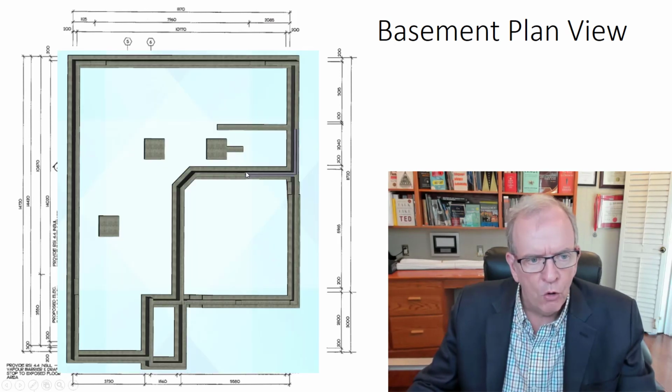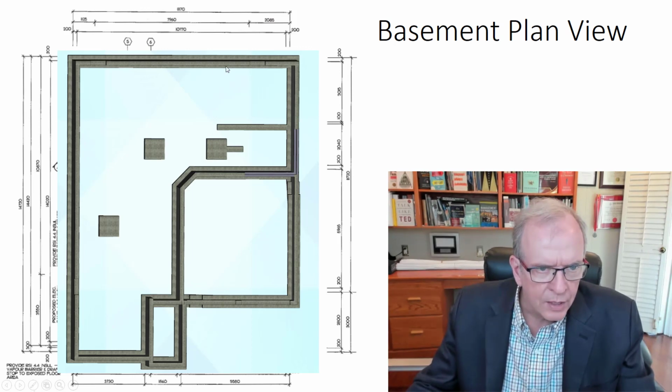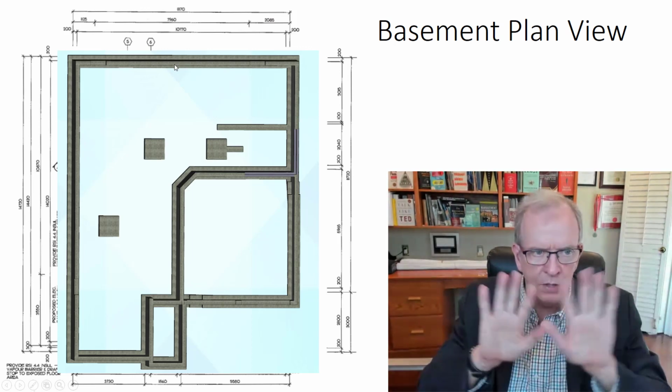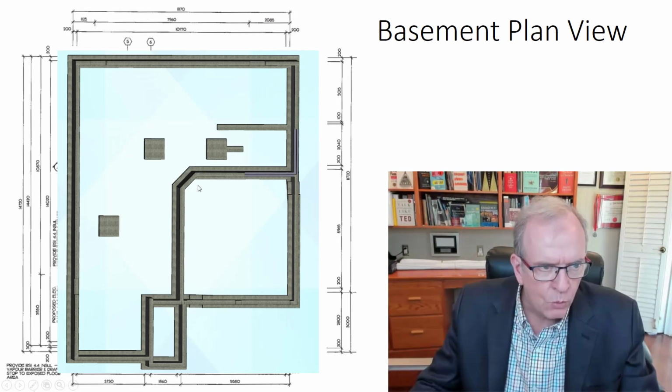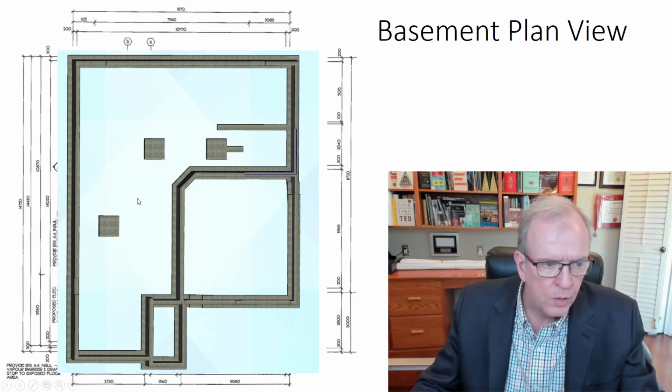I've just overlaid this 3D image of a 3D model for this particular house. You can see the outside, and it's in a perspective view, not an orthographic one, so you can see a little bit down some of the walls, and you see some shadow lines here. And you can see this little cutout here, which we'll talk about in a little while. This is for the sunken laundry area. We also see a column footing here, a column footing here, and a T-shaped column footing over here.